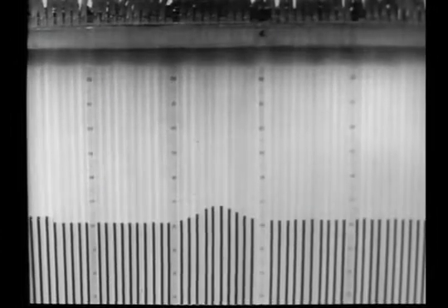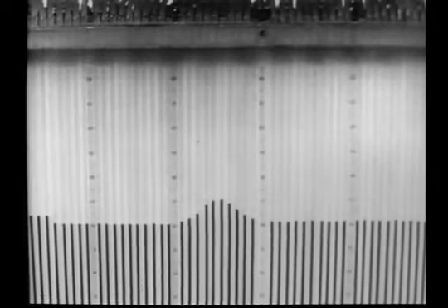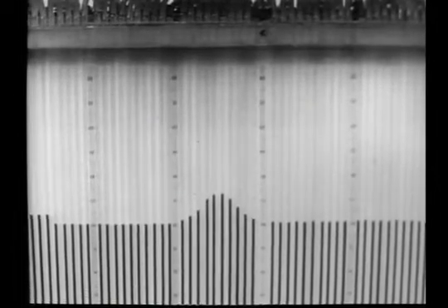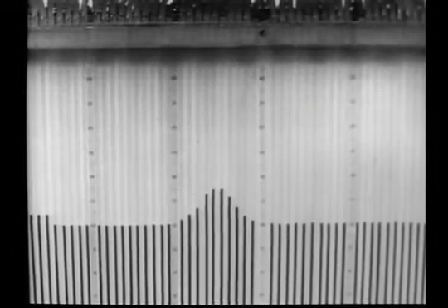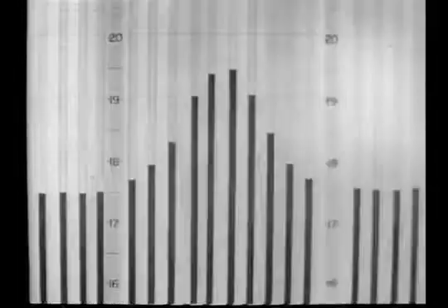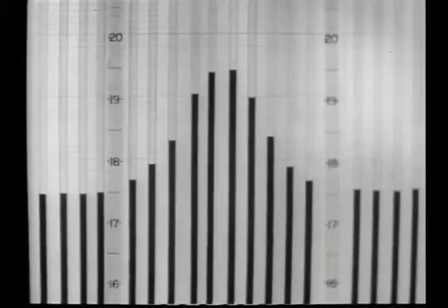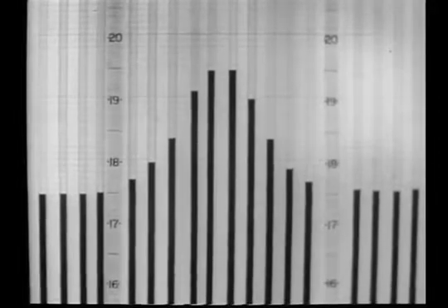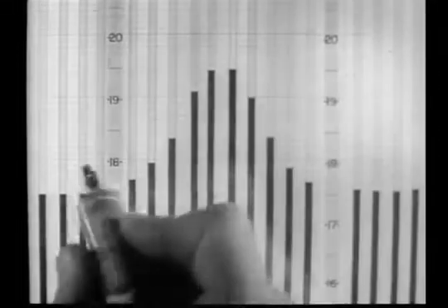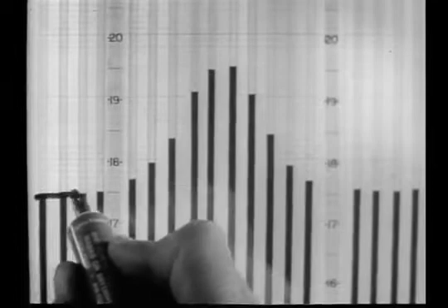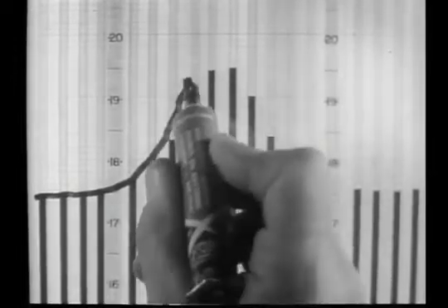The loss in total head reflects a change in streamwise momentum flux and is a measure of the profile drag. The airfoil under test is the one with its maximum thickness at the quarter chord point. The defect in total head in the wake shows up as this pattern, which we'll mark for future reference.